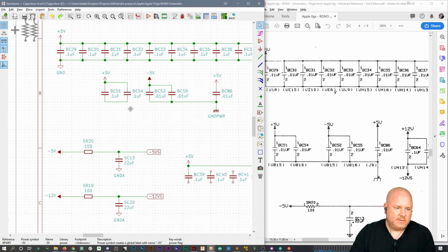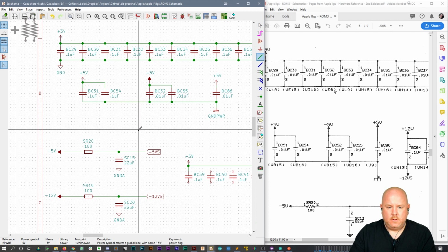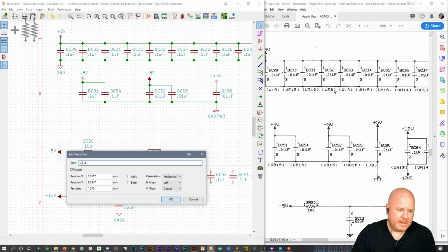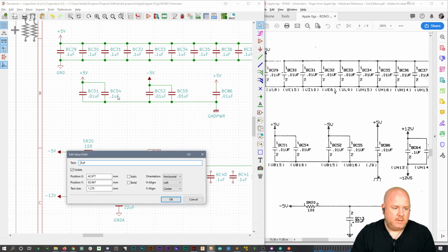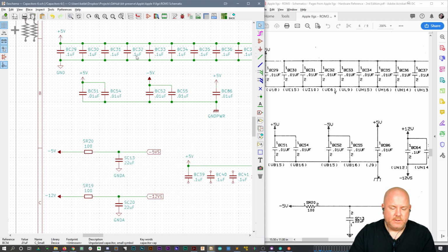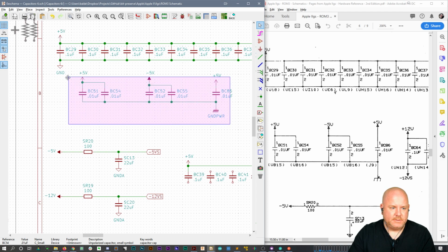I just realized I want this to be over one capacitor column. All right, and that's 51, it should be 0.0. So these must be the high frequency decouplers or filters. I bet these go in parallel with one of the ones up here somewhere. So that's plus, minus, plus, and that's all over the place, but tough.